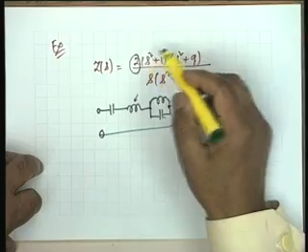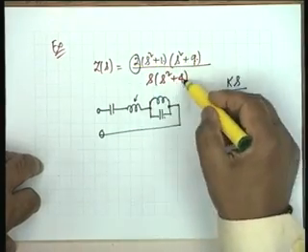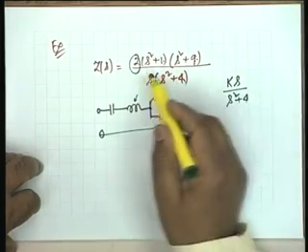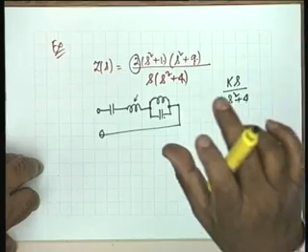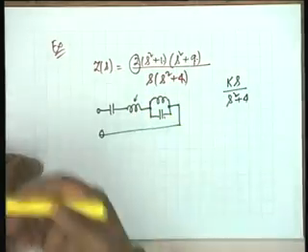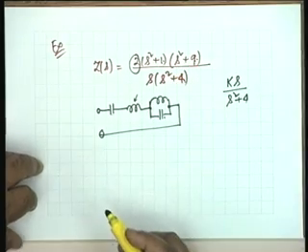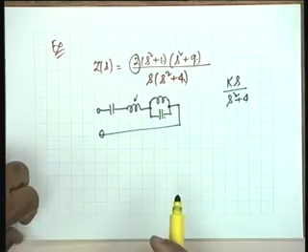All I am given is, what I need is these 4 numbers, 2, 1, 9 and 4. Just that. Okay. And if the numerator is of degree 4 and the denominator has only a pair of zeros on the j omega axis, s must belong to the denominator. There is no other way. You cannot bring s here. Then the function will not be PR, because the degree difference would be more. Okay.